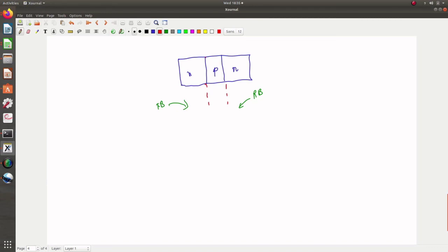Let us see how the transistor works when the emitter base junction is forward biased and the collector base junction is reverse biased. I am just redrawing the energy band diagram without drawing the Fermi level, so that on application of reverse bias we have more potential barrier at the reverse biased junction, which is the collector base junction.